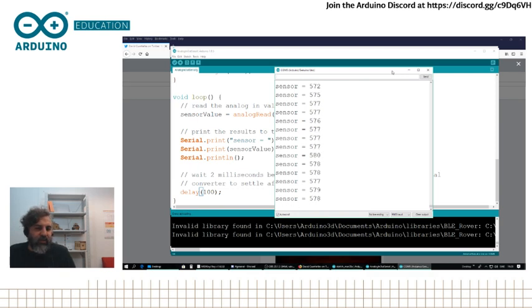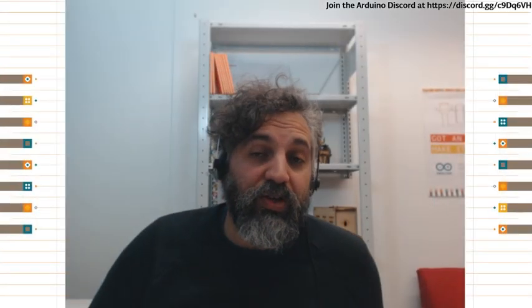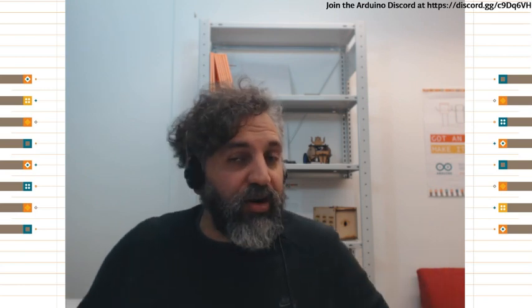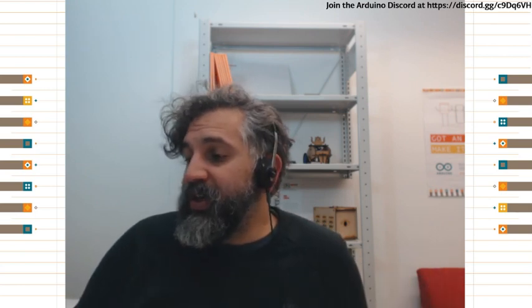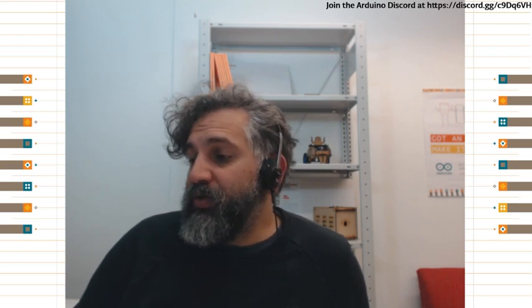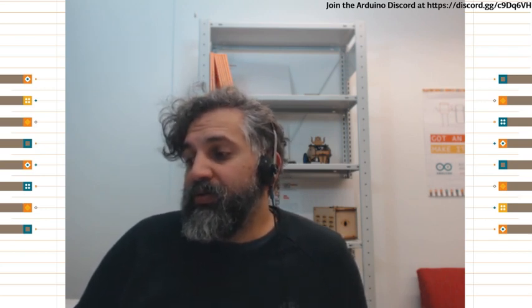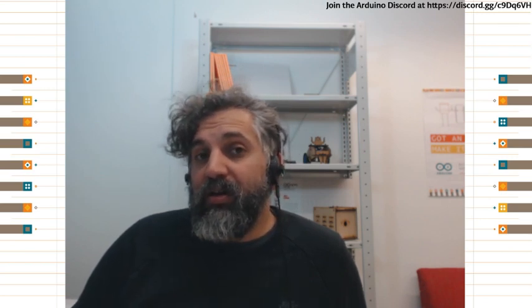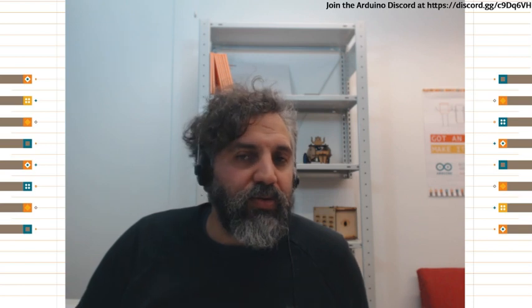and when I heat it up, the value keeps on increasing, and it goes up to like 590 more or less. So now for a difference of 10 degrees, I get 90 values. That is a lot richer, so I can do a lot of stuff. So as you see, for this particular sensor, given the conditions of the environment I'm in, it seems to be making sense to use a 10 kilo ohms resistor instead of using a 1 kilo ohm resistor, because of the richness I get from the values, which means I can play with decimals in the temperature if I want to.